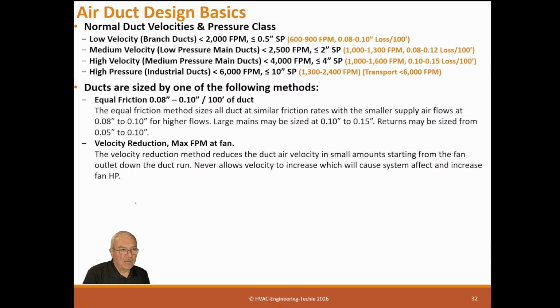So we will talk about it in these pipe design and water air design videos. But basically, system effect is any time you have a situation where the velocity is increased. Because remember, velocity pressure takes fan horsepower to do. Static is free. You take a fan, you blow the air up, you get two components. You got velocity pressure and static pressure. And as the